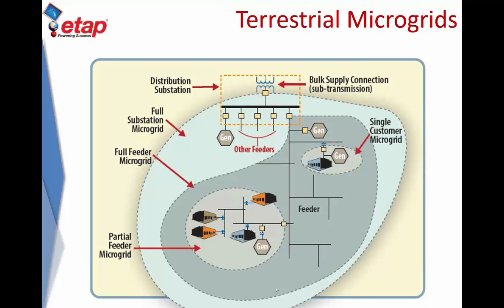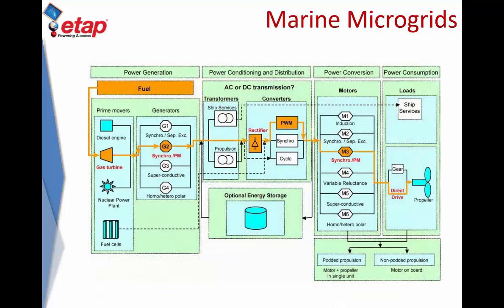A single microgrid in the system can exist on the distribution substation, but you can also have customer microgrids which are connected at the feeder level, and you can also have partial microgrids where there are multiple customers joined together to make one larger grid. Then you can essentially have cases within these microgrids where they can actually fracture and become nanogrids. But the basic definition that we'll be using through this presentation is any system that can be operated grid connected or be operated in an islanded fashion.